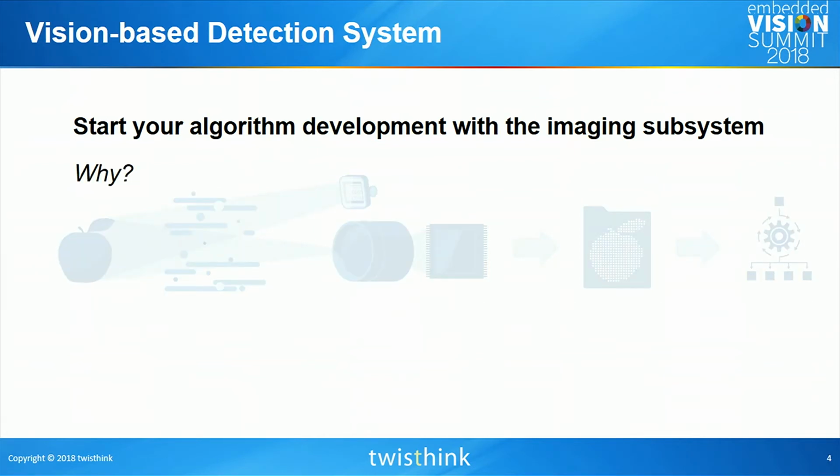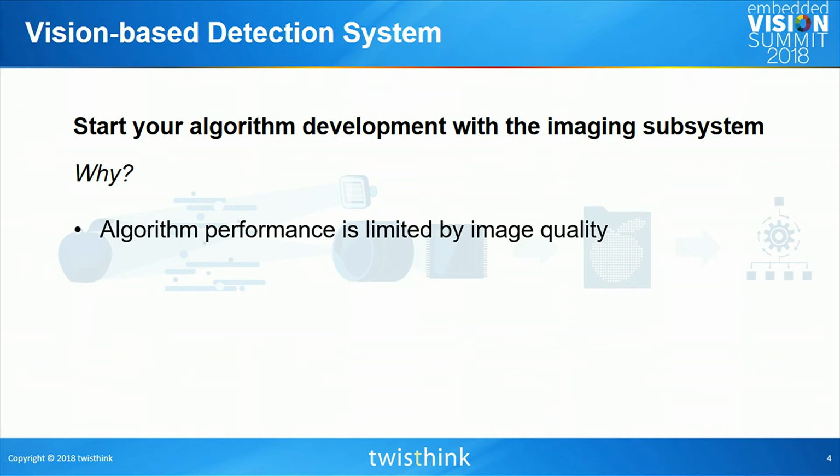So why should we start the algorithm development with the imaging subsystem? The first reason is that algorithm performance is limited by image quality. This is the garbage in, garbage out concept. You can continue to throw more capability at your algorithm, but at some point, the performance is going to be limited by the image quality that you give it. Image quality is determined by the parameters, ultimately, of that imaging subsystem.